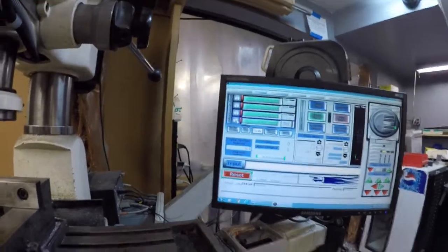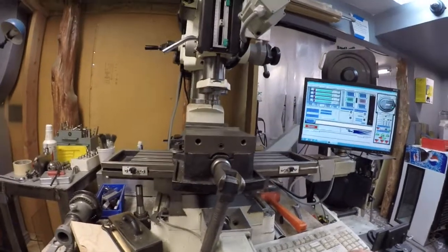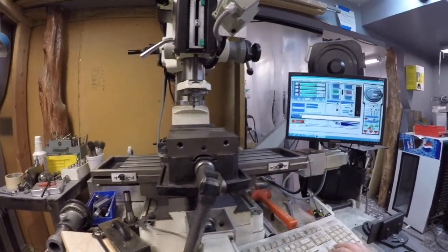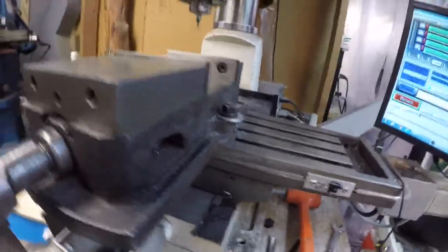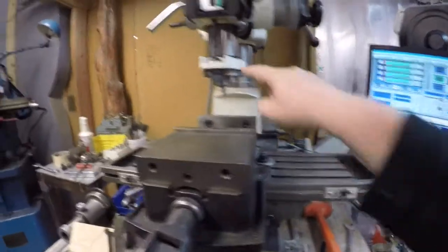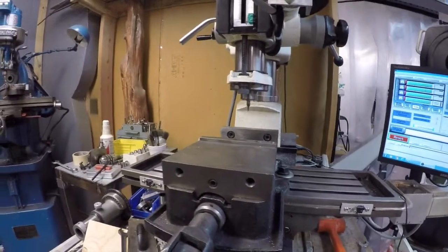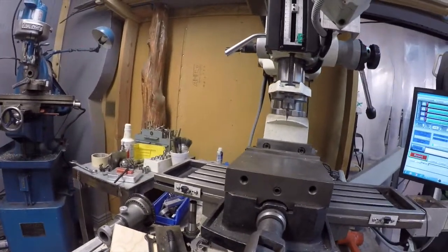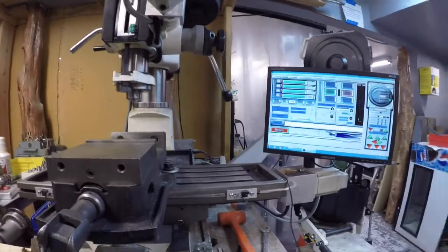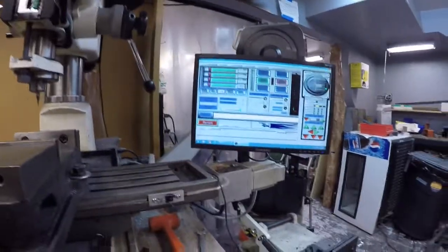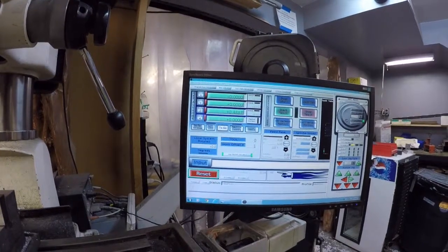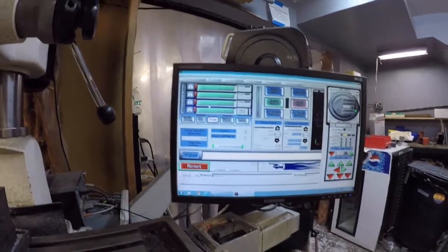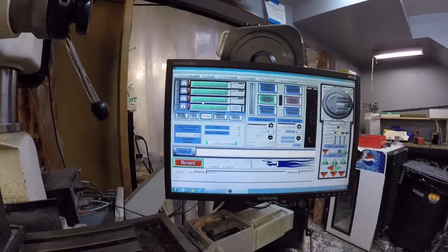You can set those things here. So for my project, for what I'm about to do, I want this machine to be about in the center of where it can, the center of everything, the center of all of its axes. So I'm going to do that. I can also move this thing up and down, so I'm going to move that up to about halfway. Okay, now the machine is about right in the center of all of the places that it can move, which is where I want it to be. I can just click these buttons that say, okay, consider this to be 0. So all of your instructions reference from this point.